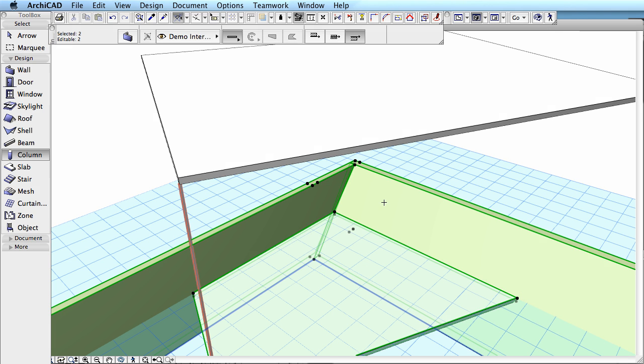the hidden element parts are shown in a lighter surface color and a dashed line type. The visible parts of the selected elements are shown in a brighter surface color and a continuous line type. The reference lines of the walls are shown in blue, while the other edge lines are shown in green.